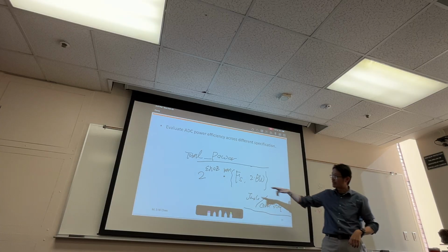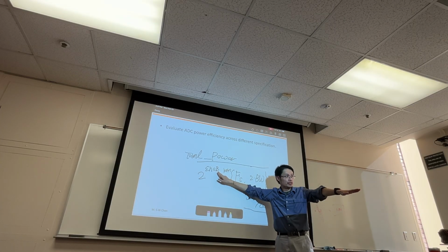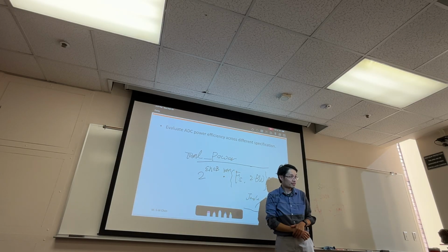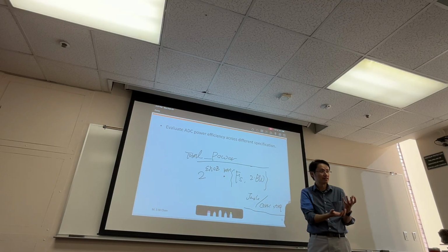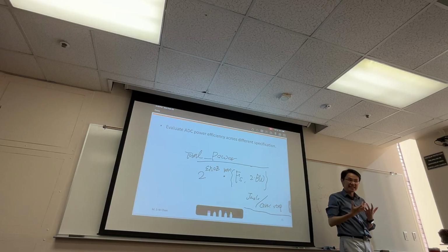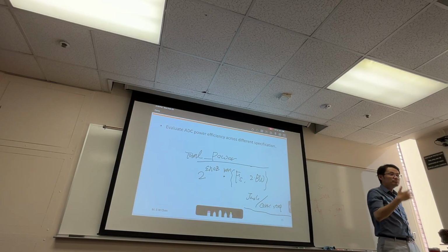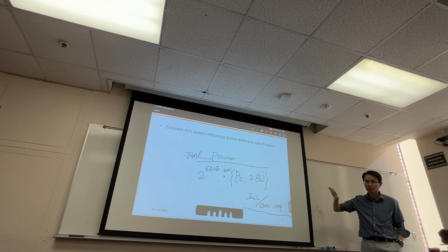So we need to divide by 2 to the power of ENOB for that reason, right? If he actually designed for 10-bit ENOB, of course you should divide by more, because he actually quantizes more levels. Does that make sense? So this is basically the measure to help people understand how amazing the ADC that you designed is. I think, period. There's no other reason why you go for this. So this is basically just an impressive factor.